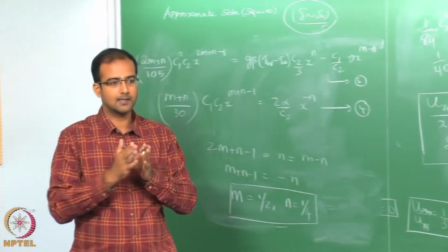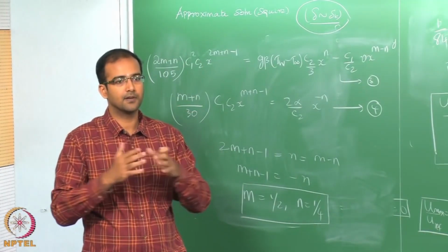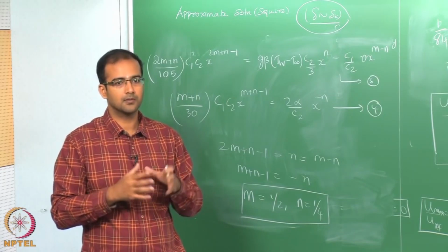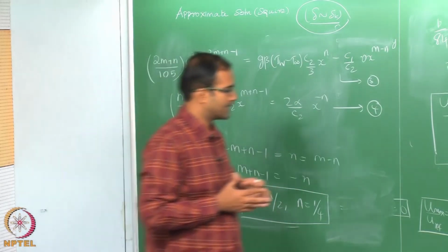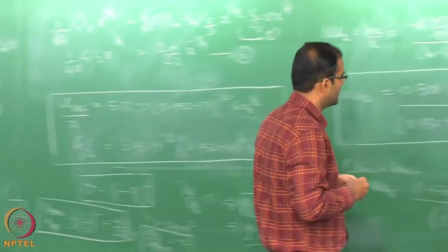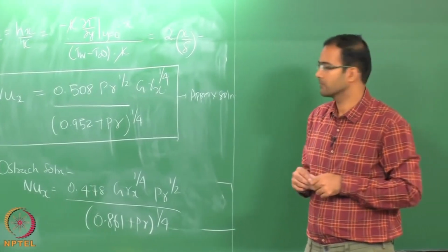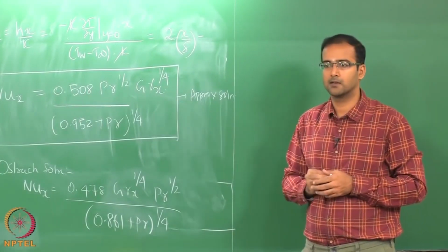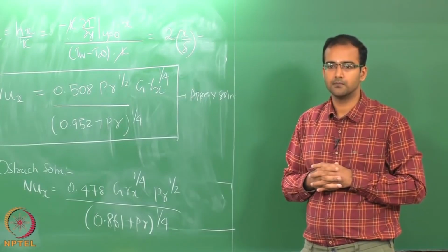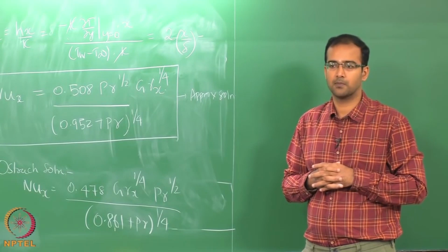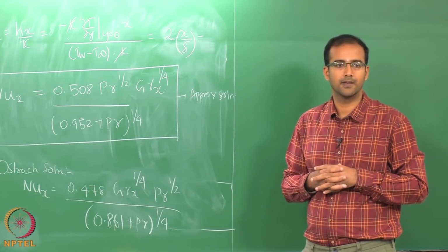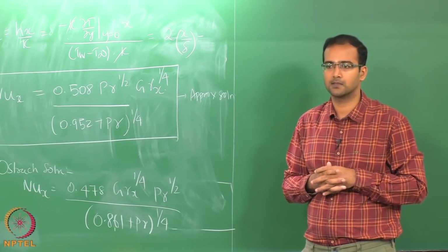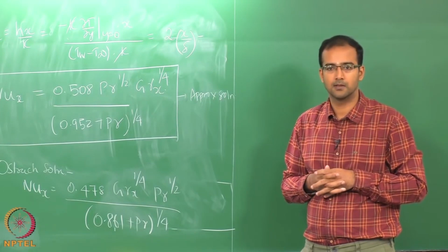I mean that is also telling you that both boundary layer thicknesses are nearly the same, so there is no point in differentiating between the two, but when it comes to the thermophysical property they are actually different. So you are correct in the sense that although we got this, we cannot use this for very low Prandtl numbers and very large Prandtl numbers. This has to be applied where the Prandtl numbers are close to 1. So in fact most of the natural convection problems are done with gases. Okay. You do not force very large Prandtl numbers or very small Prandtl numbers into natural convection mode, right.